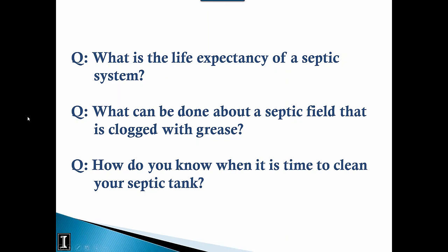But basically what these technologies usually have is the addition of oxygen into your septic tank or your distribution box to up the oxygen, which helps grow bacteria, as well as a proprietary blend of bacteria they would add to it that they say attacks that grease that was causing the flow issue. Like I said, I would definitely see if there's at least a good reputation for these, if not approved technology with the locale or the state that you're in.